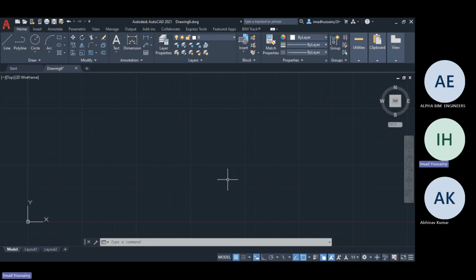First of all, coordinate systems. The word coordinate means you can imagine X, Y, Z points, like the graphing and plotting points we used to write. Once you know your project coordinates, then you can draw it easily. There are two coordinate systems in AutoCAD: one is UCS, the user coordinate system, and another one is WCS, the world coordinate system.